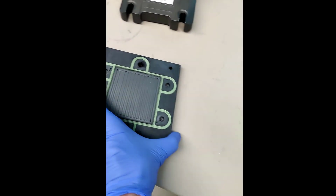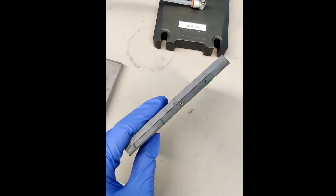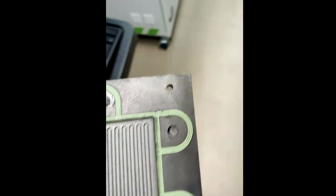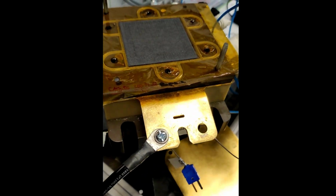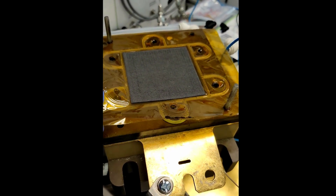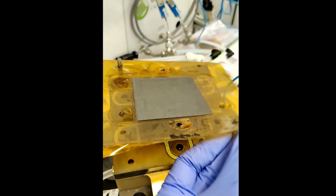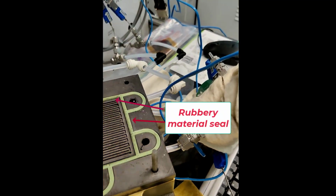The next component I'll show you here is the flow field. The flow field is made of graphite, and you can also see the thickness of the flow field. And this is how it's assembled in a cell. The MEA with the GDLs is placed on the first flow field and then will be sandwiched with the other flow field. The boundary of the active area here is sealed with a rubbery material to prevent leakage.